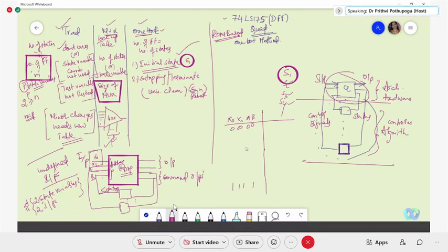So here you need to define the total table, and there is no way you can leave out any combination. That is the only drawback here. But if you have patience enough to define this table completely, this is the simplest way of implementing ASM, because nothing is needed to design here.